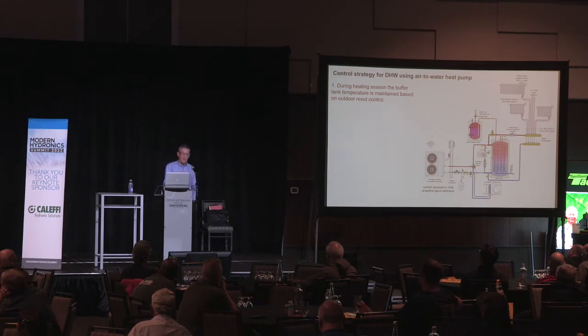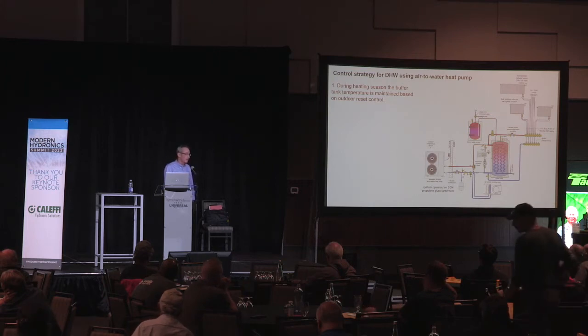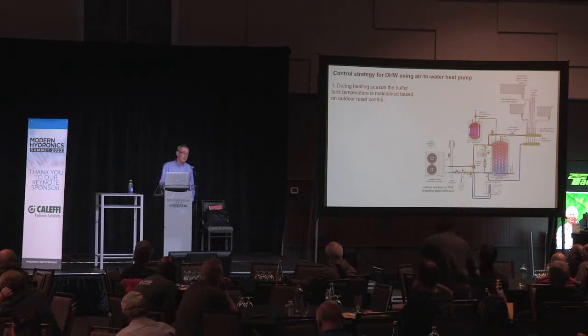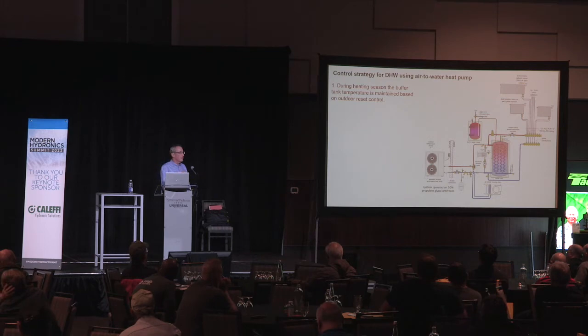Now, an inverter compressor heat pump can do that. It can vary its speed. If you want it to track, let's say, 45-degree chilled water outlet temperature, as the air handler load changes, it can modulate the compressor and do that. If it's an on-off compressor, you have to make sure that the coil capacity in that air handler is matched. Okay? It's not an ideal scenario when you have an on-off compressor. It is better suited to an inverter compressor type heat pump where, again, the heat pump can adjust its output so that it keeps up with the coil, and it simply maintains a certain chill water temperature to the coil.